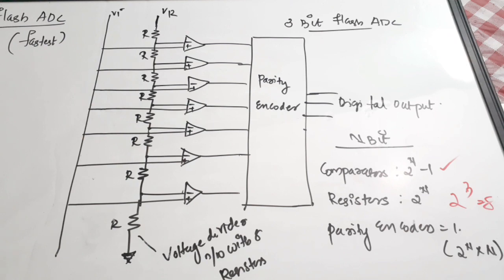Okay, so that is the general equations for a flash ADC, and just know that it is the fastest type of ADC and the complete conversion will be obtained in 1 clock cycle. Okay, so within the given general types of ADCs, flash ADC is the fastest one. And we are seeing here the structure of a 3-bit flash ADC. I hope it is clear.